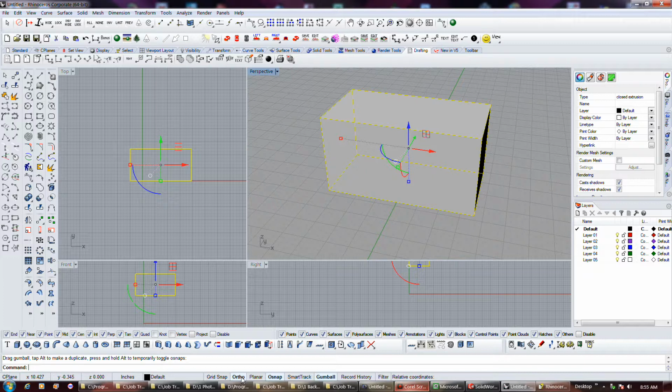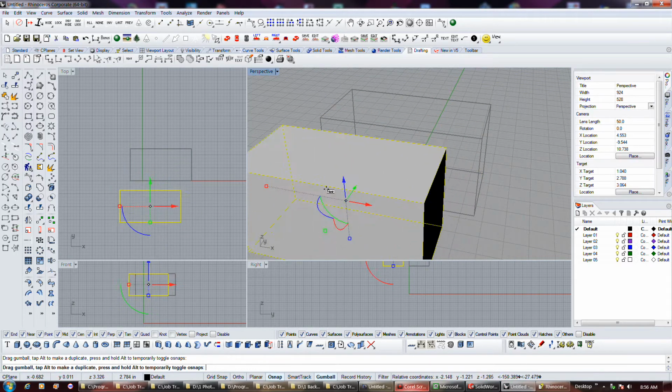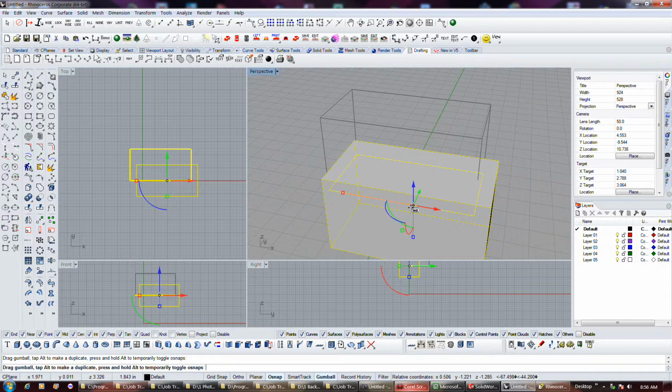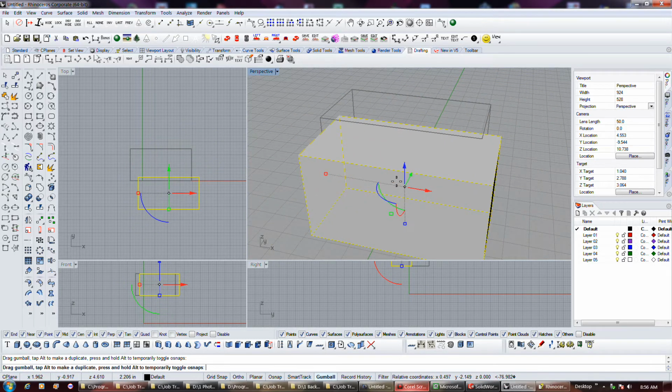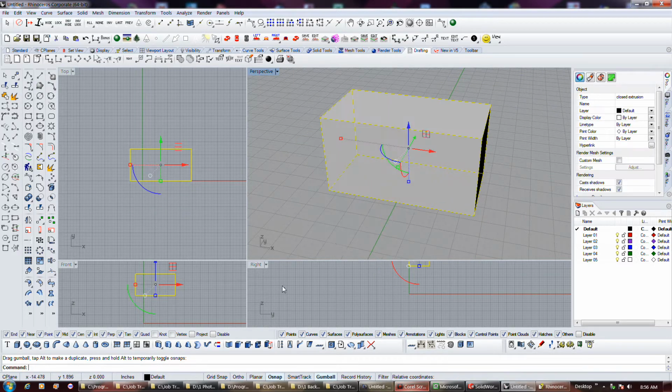Now ortho is probably one of the reasons why we're not in ortho mode anymore, so it's not really attempting to snap. We're still snapping though because of our object snaps. Again, hold the Alt key. Now I can smoothly move it around, but again, I've got ortho set to where it's incremental. It's angled ortho, so it's not the straight orthogonal. It has like a 15 or 30 degree increment, something like that. Probably 15 degree.